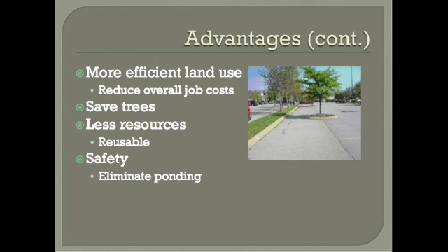As trees grow, their roots reach out at least as wide as their branches. As the roots expand and grow under an impervious surface, they get further and further from the water. The deprivation causes them to start reaching for the surface and into the impervious surface. This creates cracks in the pavement and adds to the maintenance cost. Pervious concrete allows the water to move directly into the soil and to the roots so that the tree never needs to reach for it.